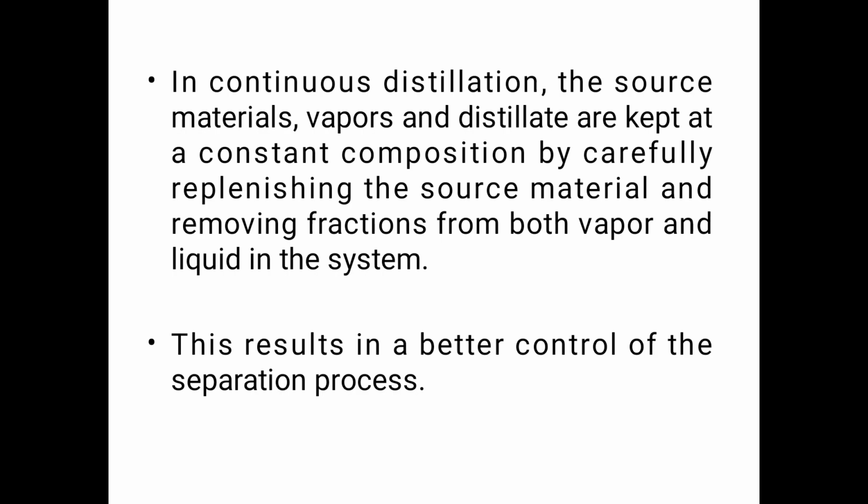In continuous distillation, the source materials, vapors and distillate are kept at constant composition by carefully replenishing the source material and removing fractions from both vapor and liquid in the system. This results in better control of the separation process. Compared to laboratory distillation, the industrial distillation is very effective, more purity of the product is collected and efficiency will be increased. The time consumed is also less.